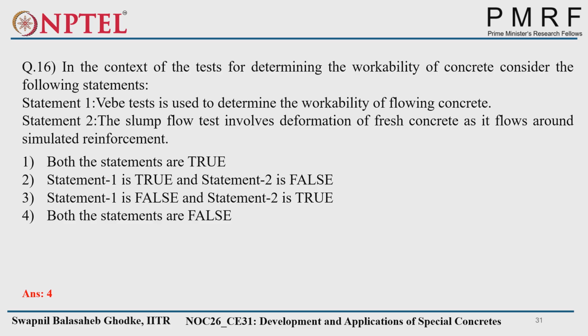Yeah, right. Similar to the L-box test and J-ring test, there are bars available which simulate the reinforcement. But in the slump flow test, there are no rebars to simulate the reinforcement. That's why the slump flow test is not used for flow around simulated reinforcement. It is only for measuring the slump flow, the flowability. So that's why both the statements are wrong.